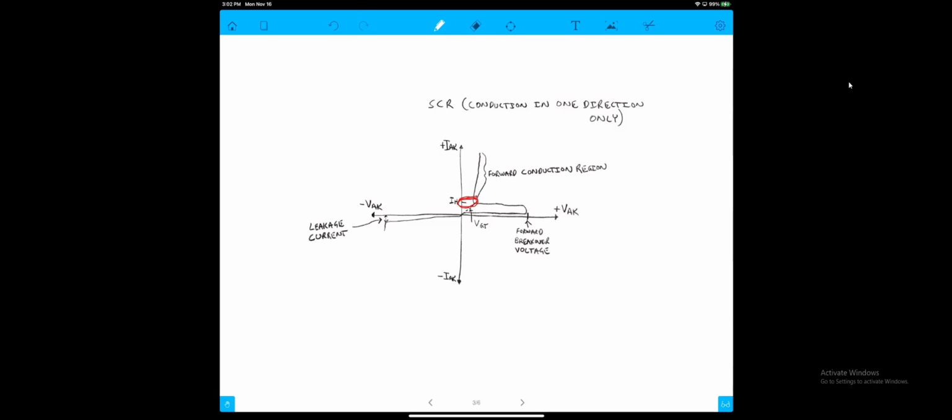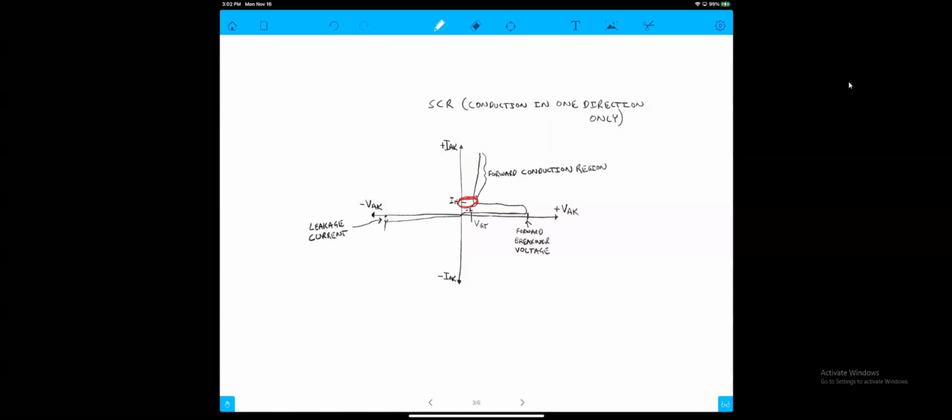So you'll keep adjusting your pot, going down, down, down, watching the LED at the same time. Good thing for us, Multisim Live actually shows the LED on and off. So you'll keep moving it down and watching the current on your meter, and as soon as that LED goes out, that's the current value you'll write down on your lab. It's pretty straightforward and simple.